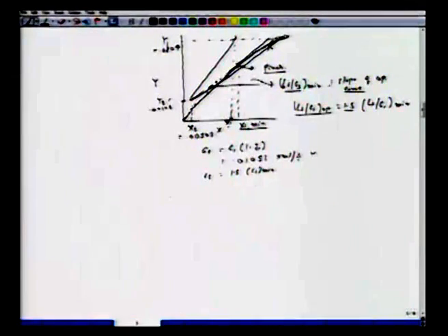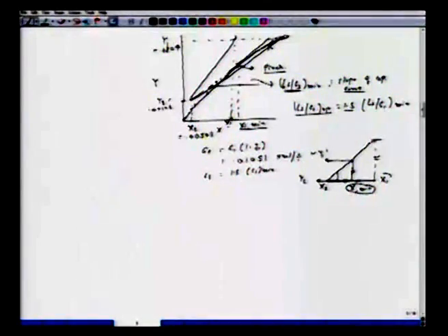So from here, to get LS minimum, the amount of solvent, you are supposed to get this slope here. How do we get this slope? Remember, this is a tangent here, and this coordinate is x1 min. This point is x2, corresponding to which we have y2. Here also we can have some y prime, and wherever it makes intersection with the curve, we have this x1. So to find the slope here, there is a tan theta. Either you go by this segment divided by this segment, or you can go by this segment divided by this segment. All you have to do is to read either x1 min or x1 here.